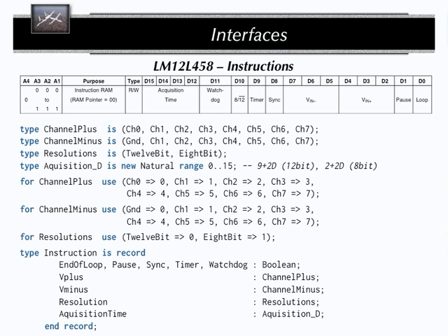So if you say that I have an enumeration type from 0 to something, that is often wrong. Because if you read these data sheets, you often have gaps in there. 0 means that, 1 1 means that, 1 1 0 means that, and the things in between don't mean anything.